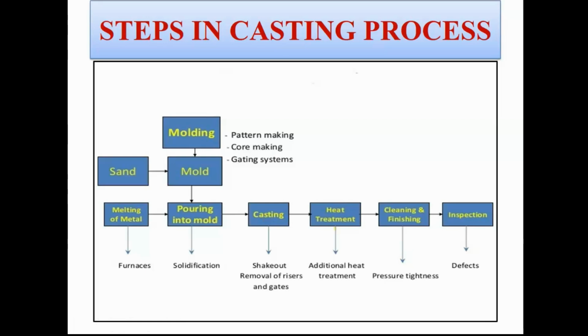So if more number of defects are present, they will promote the brittle fracture. So only the ductility or the proper amount of fracture toughness can take care of this brittleness in the cast product. So you require the proper heat treatment method, and sometimes in order to improve the hardness and the strength, some mild tempering is also performed.